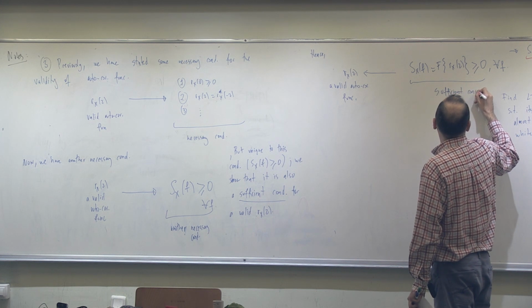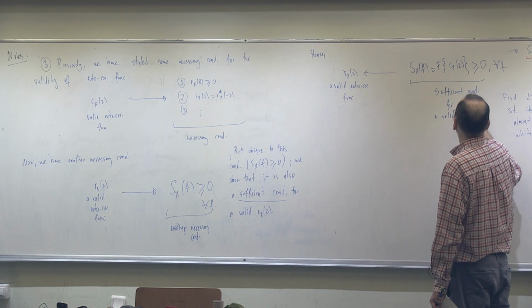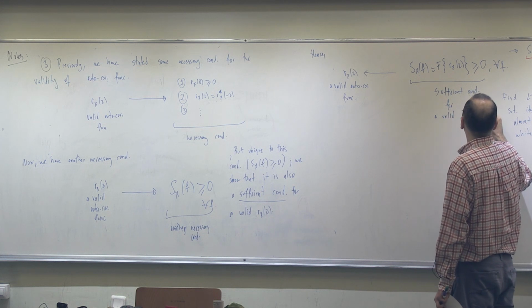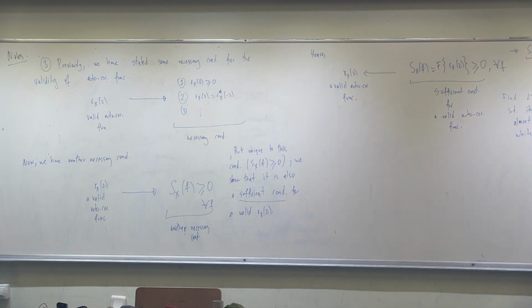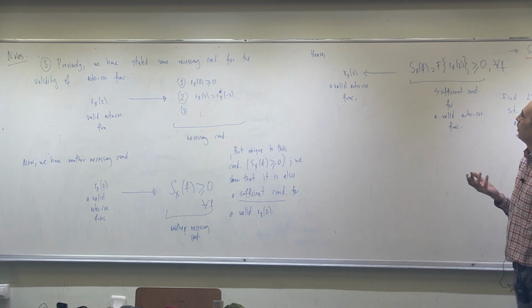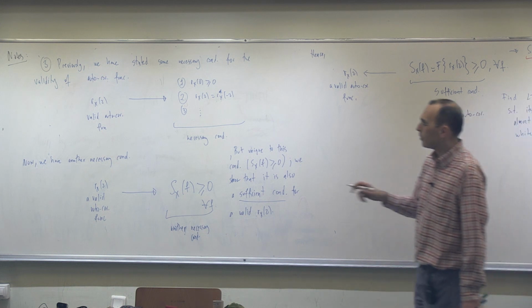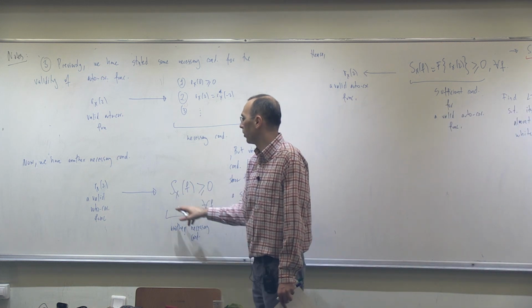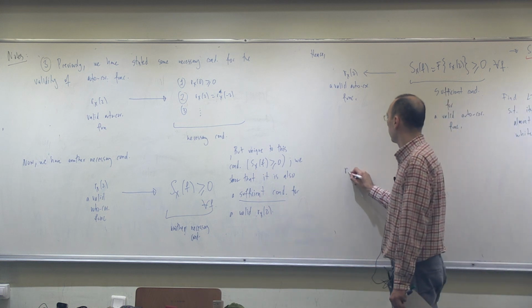Okay. Sufficient condition for a valid autocorrelation function. So if somebody gives you a function and claims that this is an autocorrelation function, then how do you test this? You can say, okay, let me calculate its Fourier transform. If that is positive, right now we have this.